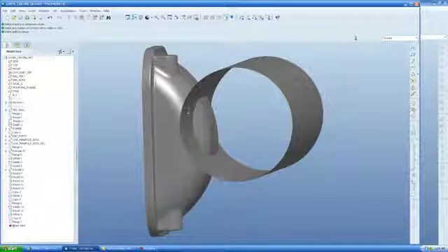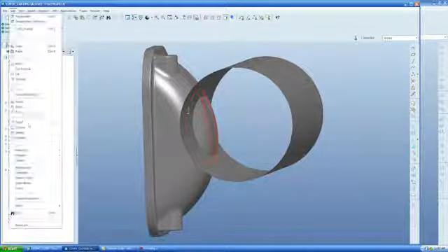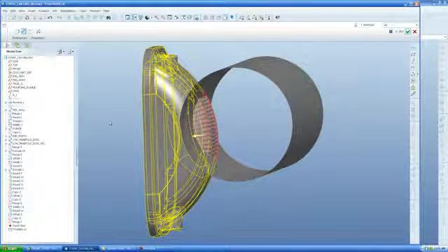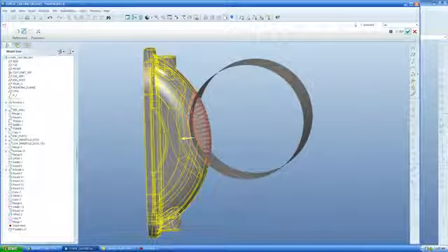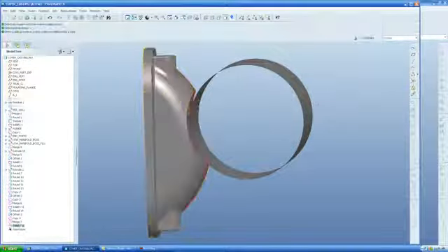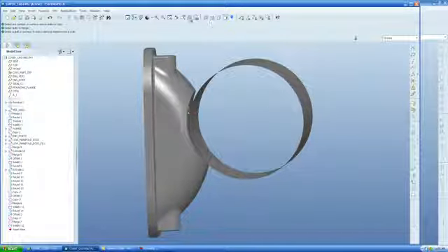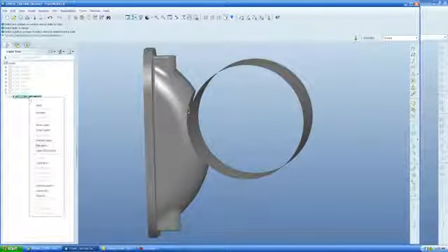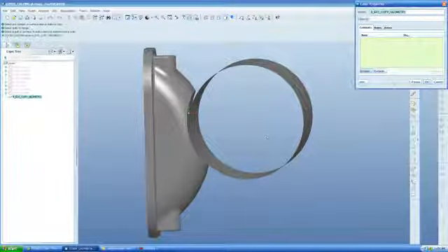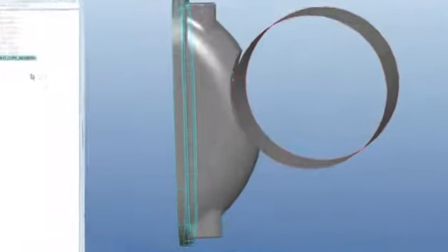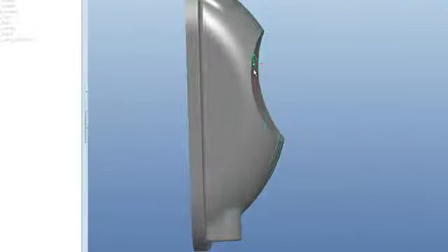So I hit OK, I select that merge, I go to solidify, and I'm going to subtract. Now you'll notice that when I go to subtract, there's an arrow here, and depending which way you have that arrow, it's letting you know which way it's going to subtract the material. So now I'm going to put this original copy geom on this layer here and hide the layer so you can see the final product here. Hit OK. I'm going to hide that layer and save the status.